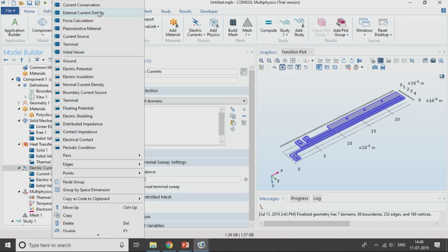domain conditions. So, you can see the cylinder which is fully filled is a domain condition, that is it can be applied on the complete volume. In the bottom node you can see the cylinders with half filled, those are the boundary conditions, that is you can apply on a particular boundary. Then we also have edge and points. As of now, let us apply electric potential boundary condition.